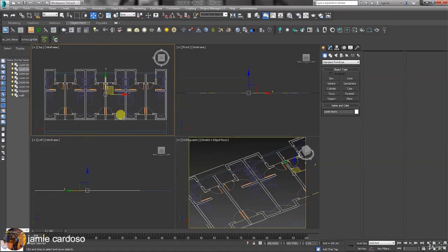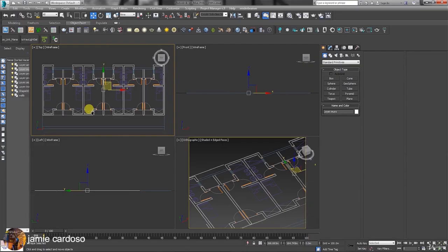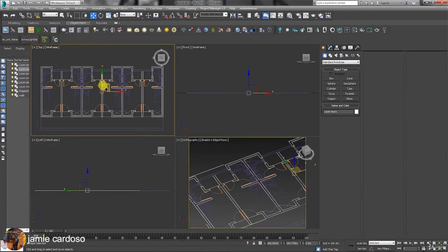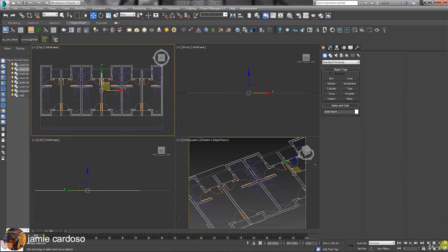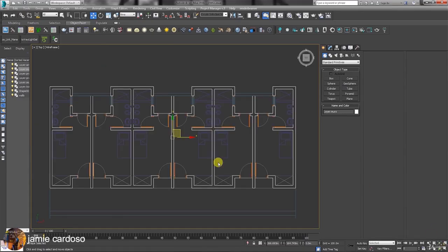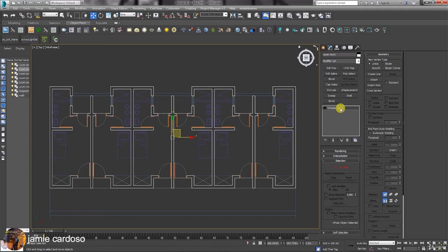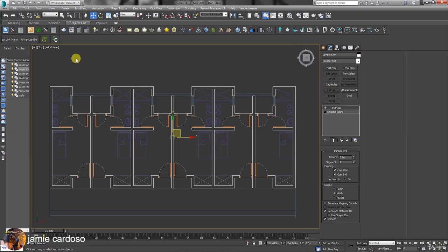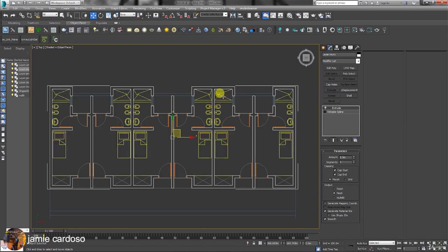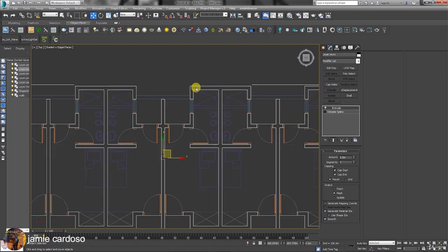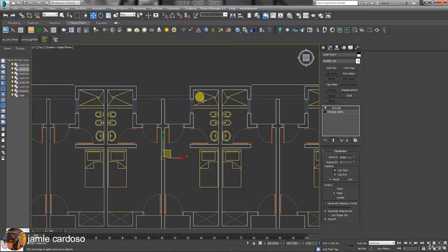This is another example for users in ArcViz industry, whereby you'd normally import a DWG file into 3ds Max and trace over the splines. Users trace over the splines because they're often overlapping and can't be extruded correctly. As an example, if you were to extrude these walls and turn the viewport to shaded, you'd quickly realize that the inside walls are not shaded. The spline edges have been extruded but not inside. This often happens when vertices are not welded.